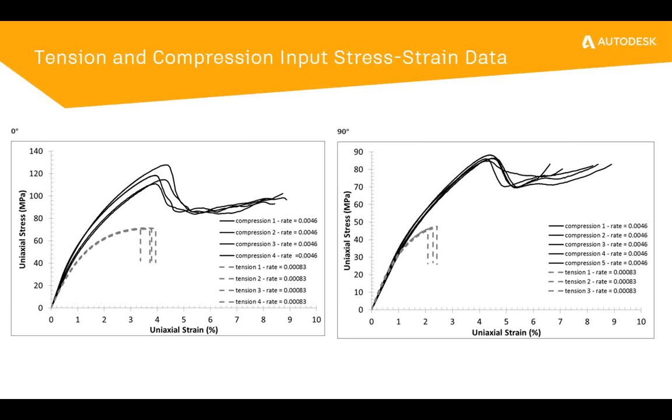And one final aspect I'd like to point out is how these plastics break when they do rupture. You can imagine in tension that once we start to get rupture, the parts separate into two pieces. We have this immediate drop off to near zero. That's where these downward vertical lines show up on the tensile coupon behavior. But in the compressive behavior, it's a little bit different.